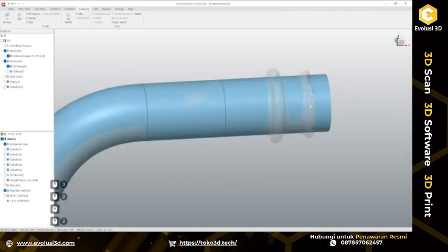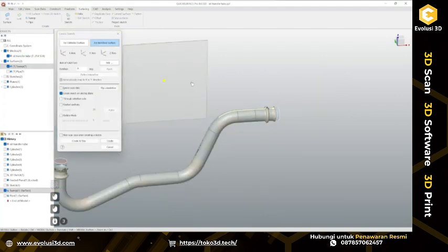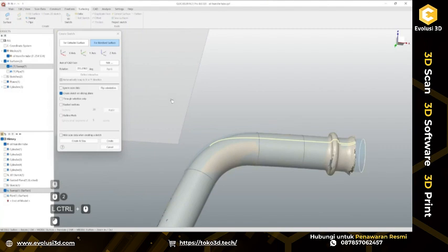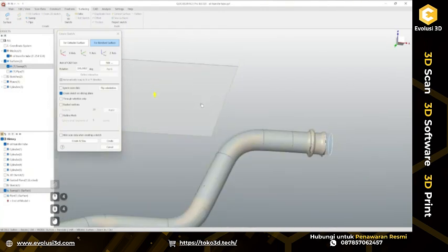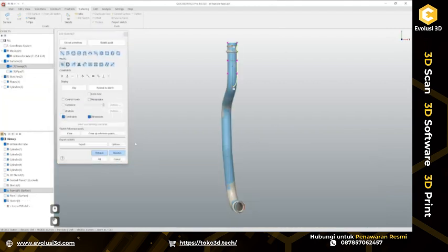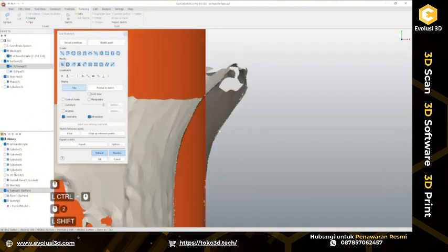Right now I just want to recreate these ends of this pipe, so they are slightly flared. Let's create a cross-section sketch here. See somewhere where I have more or less decent information available. Slightly more. Now, okay, this should be good enough. So let's enable clipping. Fit here a straight entity. Like this. On the other side, I'm going to intersect this with the pipe itself.